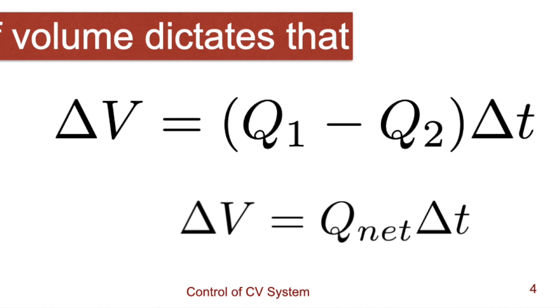That simply says if there's more flowing into a chamber or a segment of vessel than is flowing out, then over time, the volume has to increase. And it increases to an extent that is dictated by the compliance. And that compliance we can also use to calculate the resulting pressure that will arise from a change in the volume brought about by more flow going in than going out. And that's how conservation really plays out in mathematical terms.